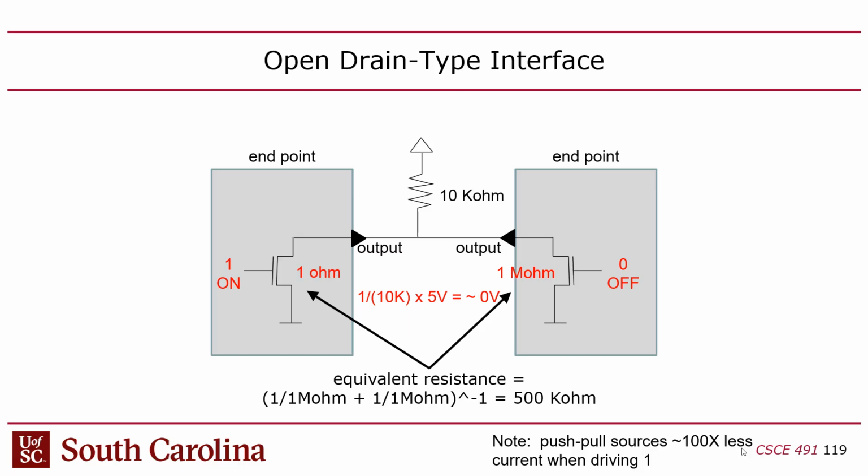Because if both of these guys pull down at the same time, there is some mechanism for that to be detected. So if there's a collision, it's detectable, in which case, well, I don't know what happens. And frankly, I don't even know how it's detected. Somehow the drivers in here can detect collisions, like if you have two potential masters that try to take control at the same time. They're both pulling down, both trying to be masters at the same time. Yes, that's the idea. By pulling this down, it's like I'm taking control.